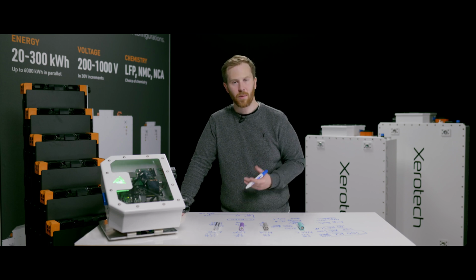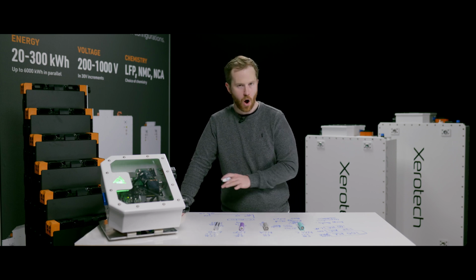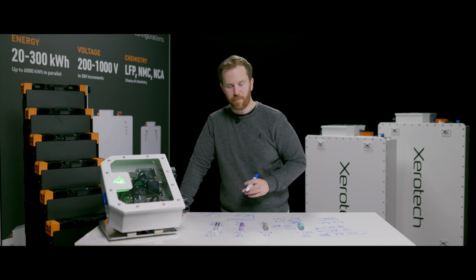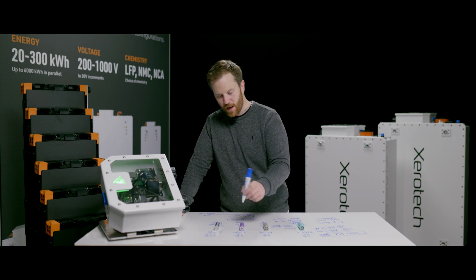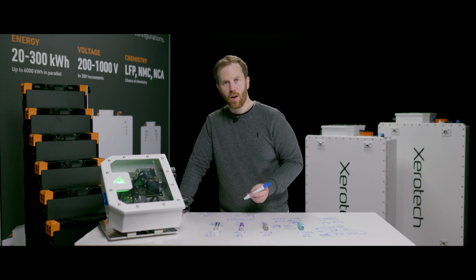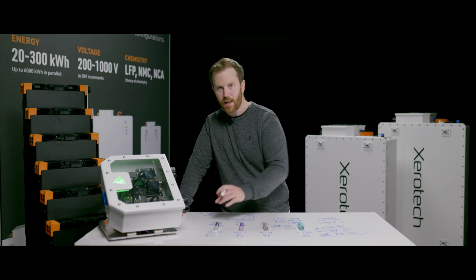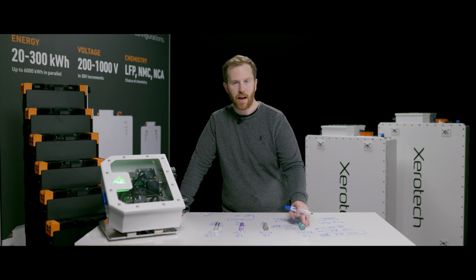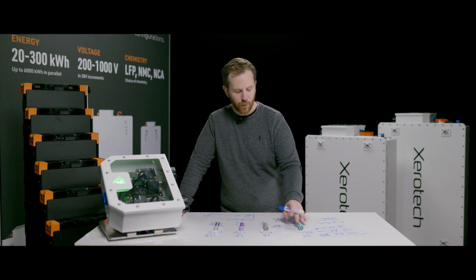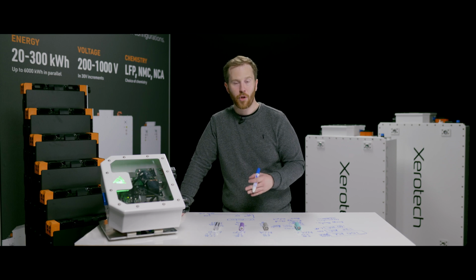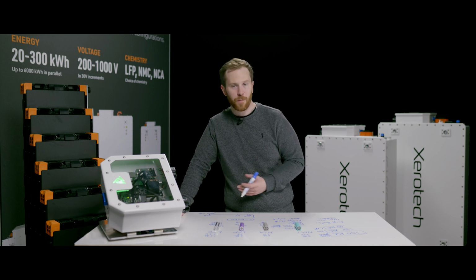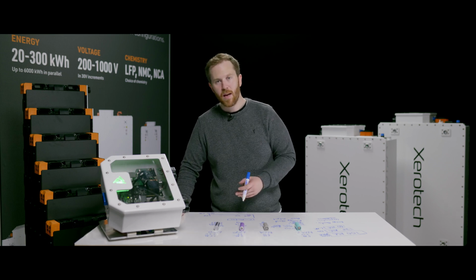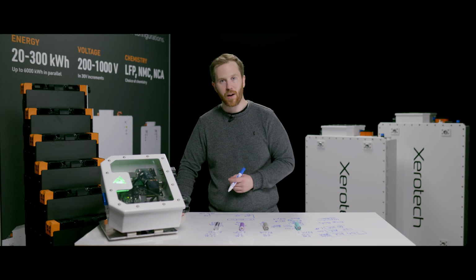but it can burn. And something I tell everyone in the battery industry is all battery cells can burn, given the right conditions. But with LTO and LFP, they're more robust in terms of a nail penetration or a crush or abuse conditions. They're less likely to result in a thermal runaway. Whereas NMC and NCA have lower stability, meaning that if they reach a certain temperature, a thermal runaway temperature, around 150 degrees Celsius, they can catch fire and burn. Whereas for LFP, it's a couple hundred degrees, and LTO is even higher again.